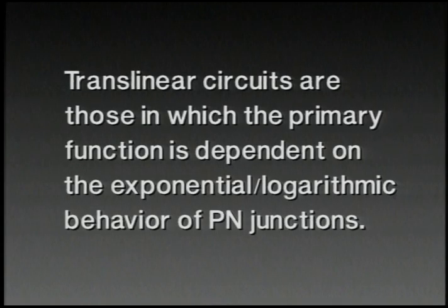So we can put that in words as follows. Translinear circuits are those in which the primary function is dependent upon the exponential or logarithmic behavior of PN junctions. Now that's not the original definition of the term translinear, it's a rather more general one. It, you note, does not refer to closed loops of junctions. That's something we'll get around to in a moment.